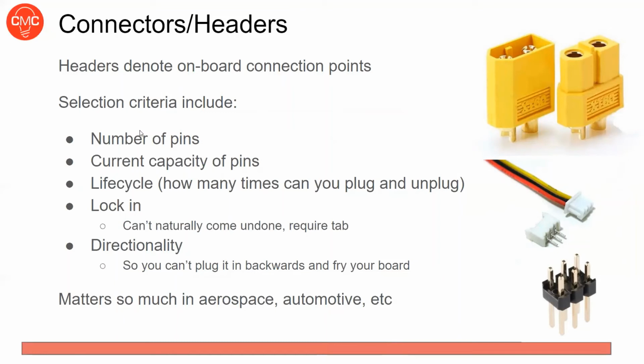First and foremost, obviously, you want to have the right number of pins, but there's a ton of other things to consider when you're picking your connectors, like the current capacity for each pin on the connector. So it needs to be rated high enough to handle your operation. You don't want to connect a huge motor to a tiny current limited header. It would burn up and could possibly cause a short. I've melted headers before because they're just plastic a lot of the time.